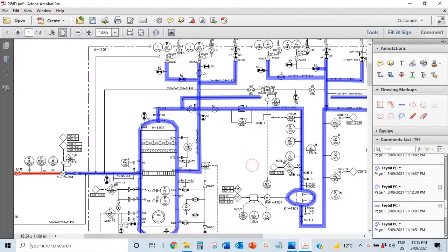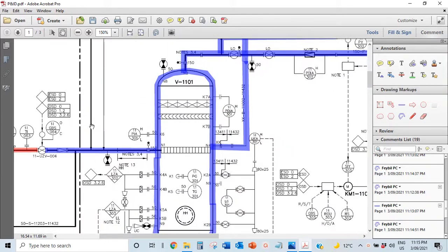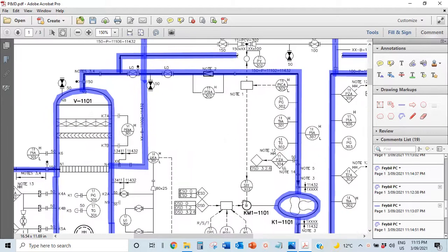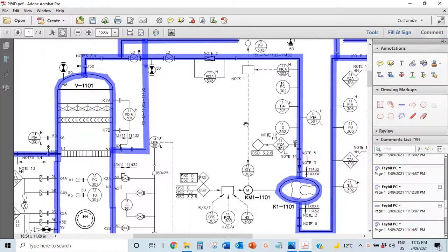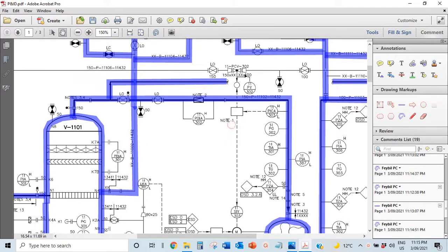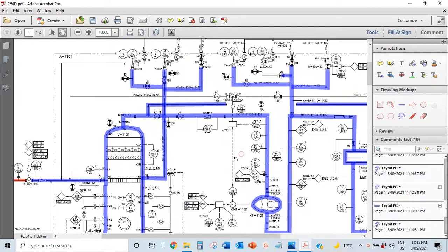Should I say, which controls the compressor motor, so that if the pressure here is low, it doesn't work too fast, and if the pressure here is high, there's a lot of gas, it works faster, so that you're not just pulling and creating a vacuum. So that's what this is kind of controlling. It keeps that back pressure here that controls that valve.